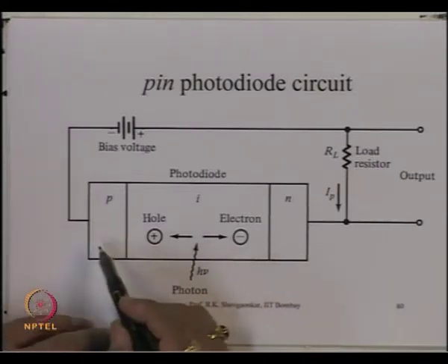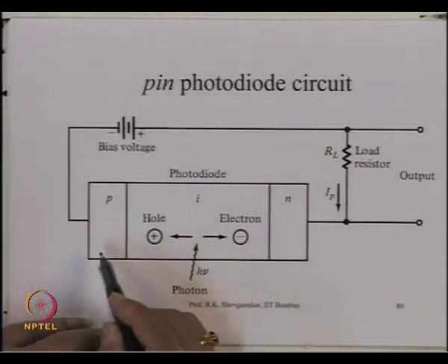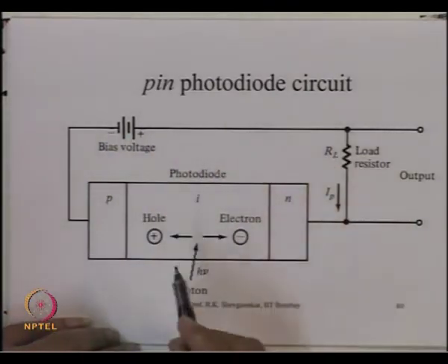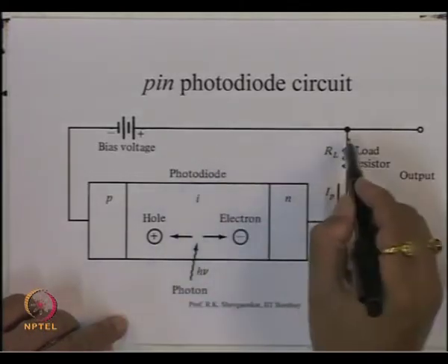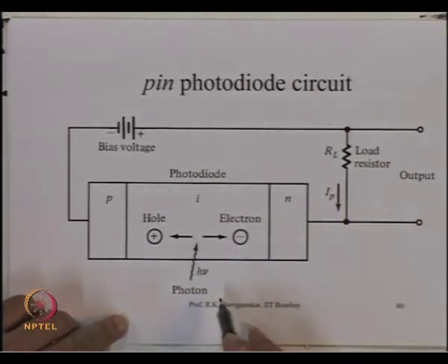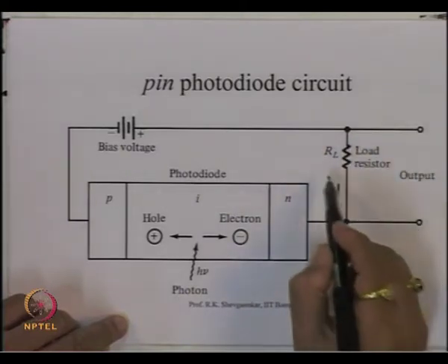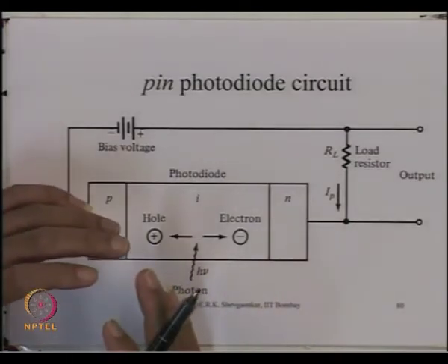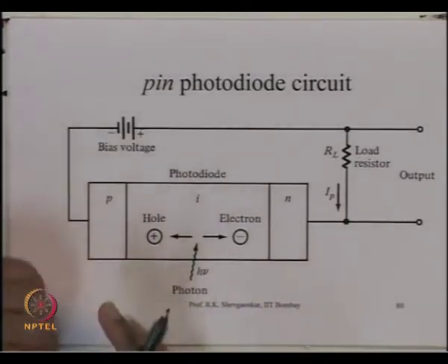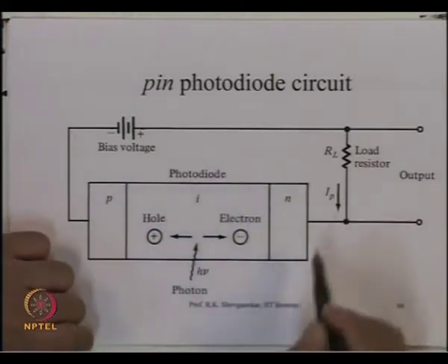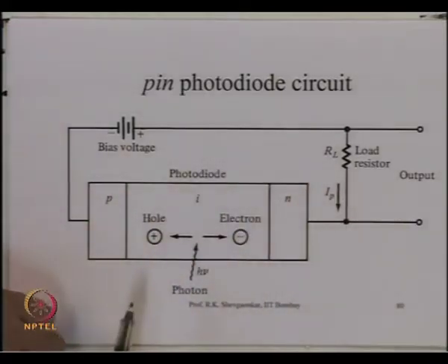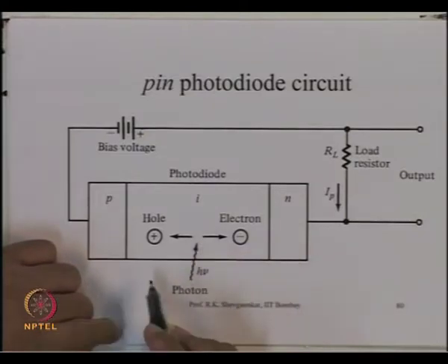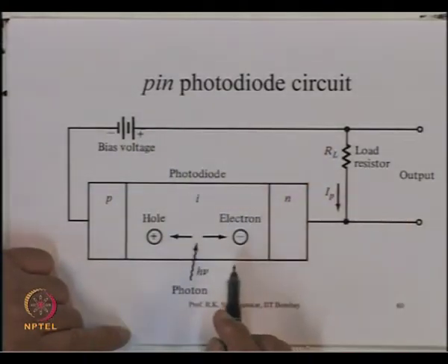Once we get that, then this reverse bias junction has a current in the external circuitry, and the current flows through what is called a load resistance. So you have a voltage developed across this resistance here. So basically this conversion process of light to electrical signal is basically photon to current generation. That means this device essentially is a current operated device, or for a given photon flux essentially we have a constant current source here.